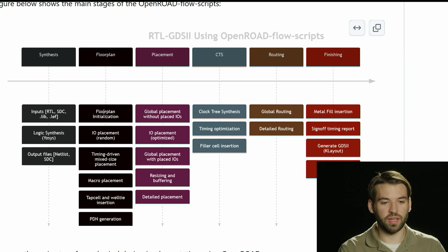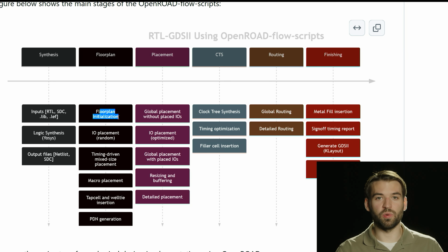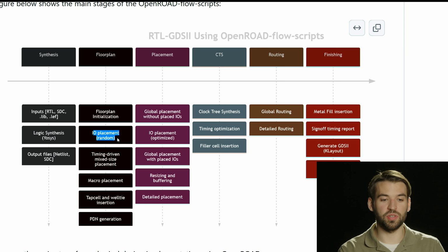You're basically doing this initialization step where the user will specify what are the area constraints on your chip, how you're setting up your cell sites, your cell rows, any margins, basically setting the stage for where everything can be placed, where the pins for the design are going to be placed. So you have your list of inputs and outputs.